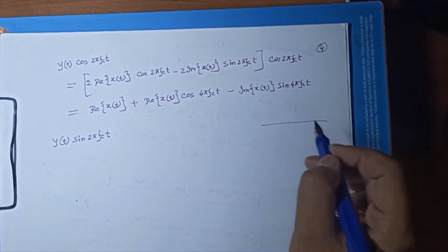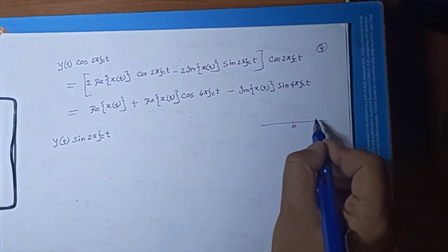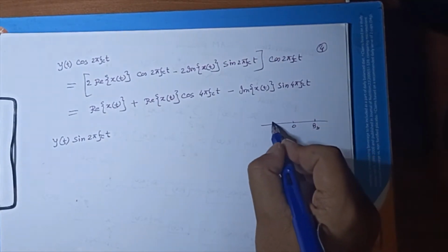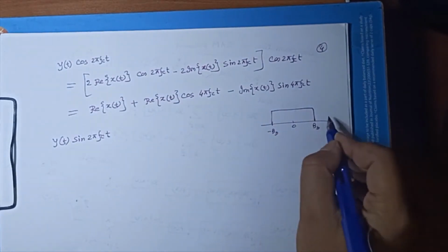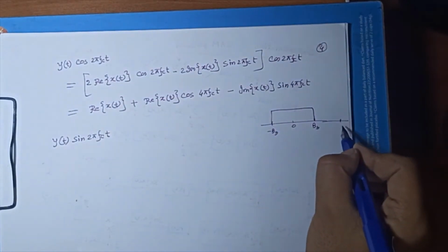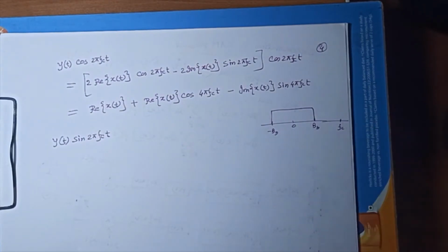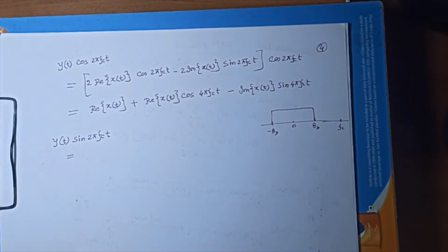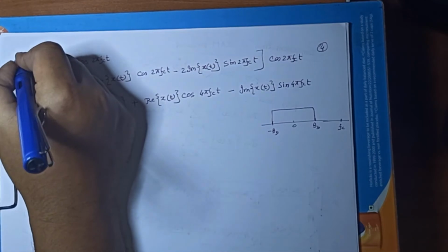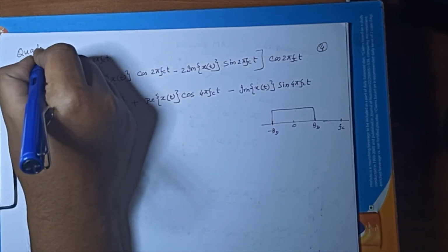So what kind of low pass filtering do you have to do? You just perform some low pass filtering here. That will work because your fc is far away. So 4 pi fct, that is far away. Both sine and cosine terms will cancel out if you perform low pass filtering. So you will get the real part over there. For the imaginary part, I will multiply with sine 2 pi fct. So I need the quadrature carriers. So I can say quadrature demodulation.